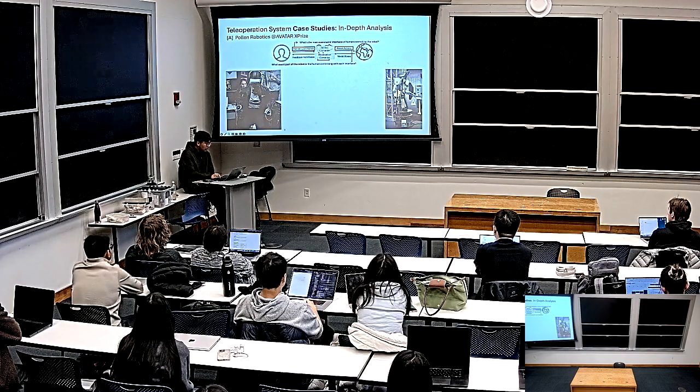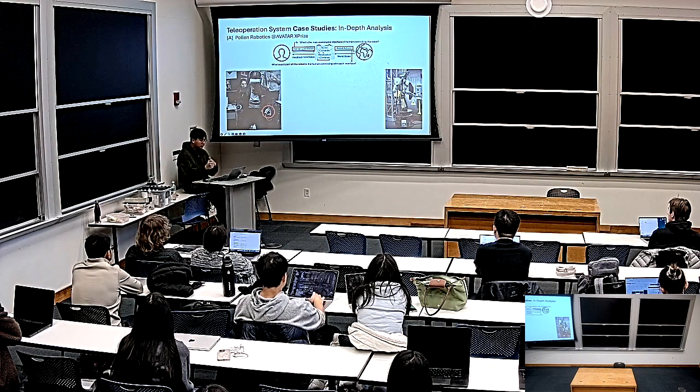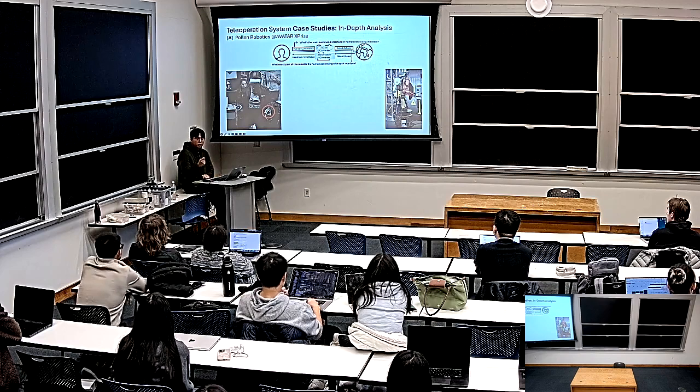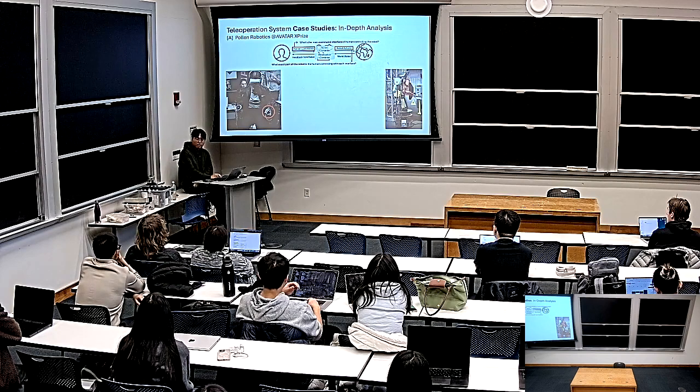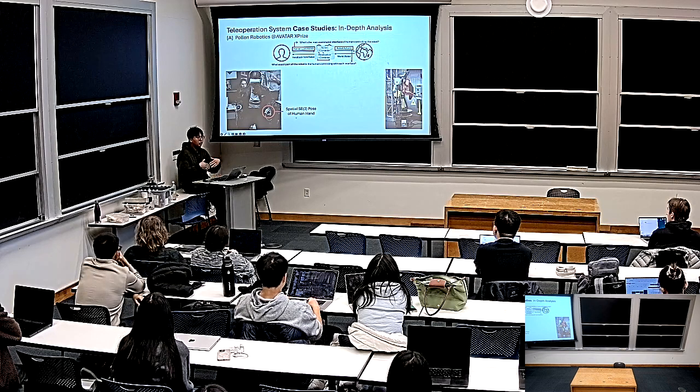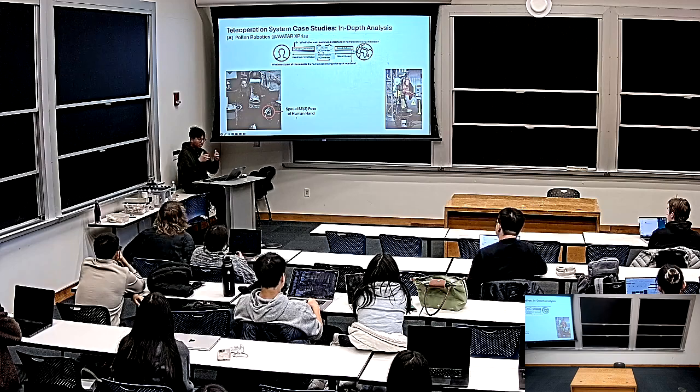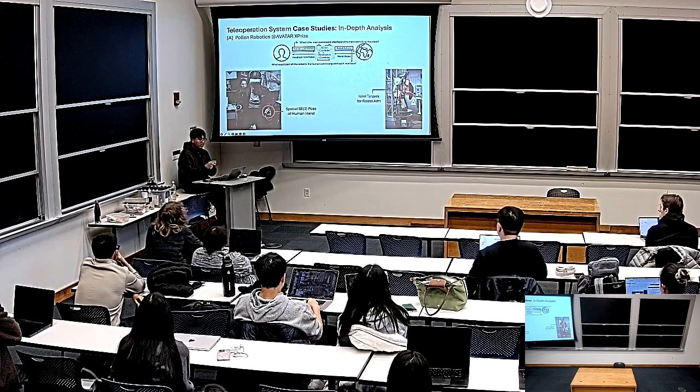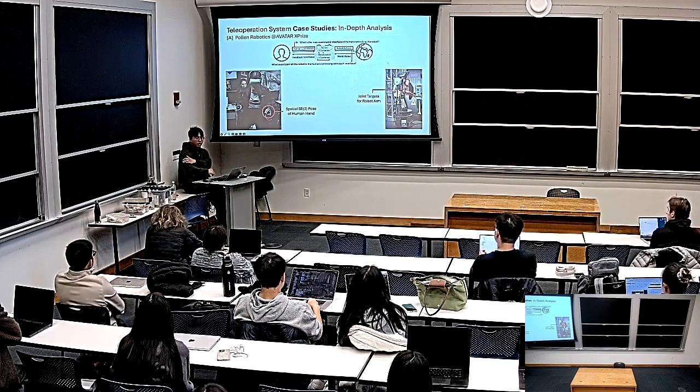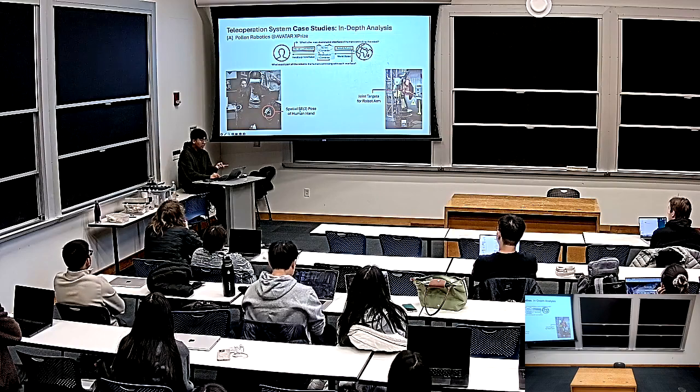And if you look at it, the first thing you can see is these VR controllers. And this VR controller is first of all mainly controlling this arm over here. As you move around the VR controller, the arm also moves. And what do you think it's actually tracking? This VR controller is streaming the spatial SE3 pose of this human hand. And that has to be somehow transferred to the joint targets of the robot arm. So that's the robot action, and that's the human command being sent.